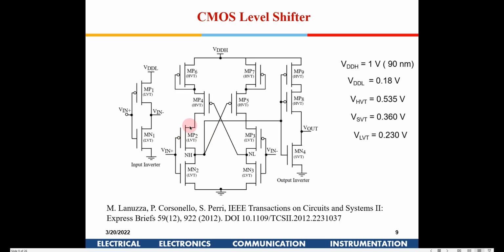And we also saw in our schematic trigger design, when we discussed that inverters can work in the sub-threshold region also, right? Provided the VDD also has to be brought down accordingly. Now here, to bring down the VDD, diode-connected PMOS have been used. What is the diode-connected PMOS? If you see here, this is the way, and HVTs have been used.